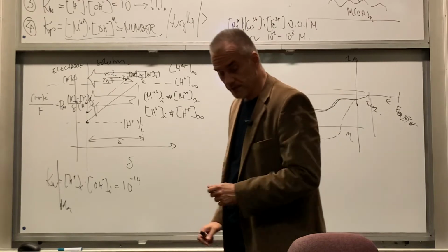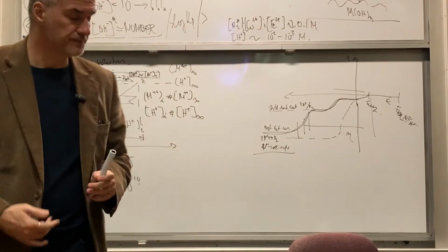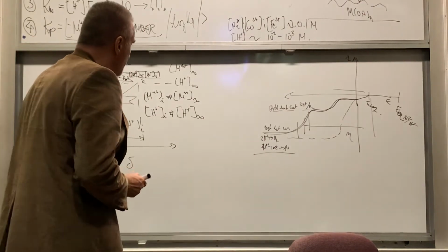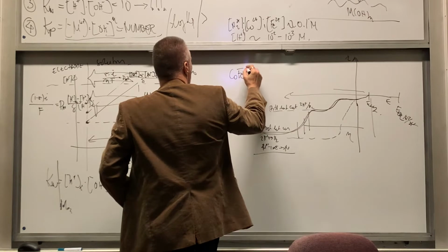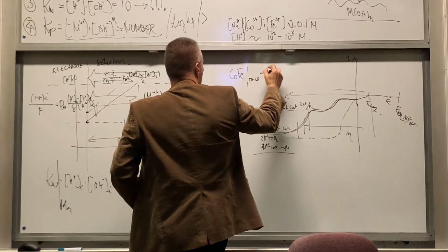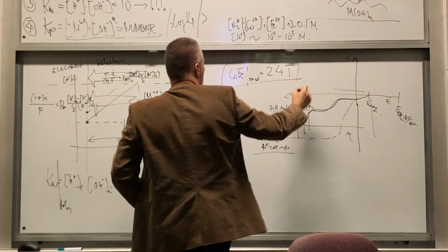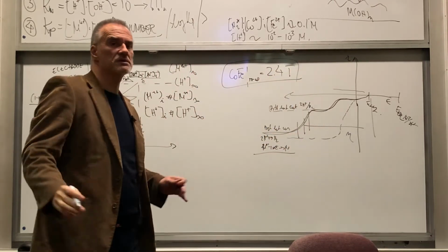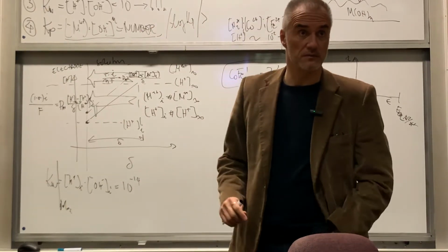When I was in Seagate, and I'm telling you personal experiences, cobalt iron, probably like 50-50, right? To make a story short, had a magnetic moment at 2.4 Tesla. It's at room temperature. This is the highest saturation magnetization that you can achieve in any material, right?